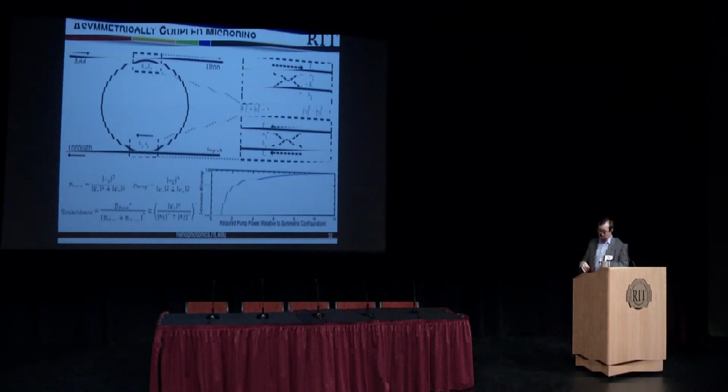And then this gives a little bit into the idea of how we can potentially engineer this. So here is a bit more complete model of the ring resonator source. Essentially, you see that we can maximize our coincidence efficiency if we make this coupling much bigger than the coupling into the ring. So if this coupling is very weak, we won't get the photons coming out there. But that comes with a big trade-off. We need to be able to get the pump in there in the first place. So as a result, yes, you can get all the photons going the way that you want them at this drop port, for example, but you need to essentially use infinite pump power to do that.